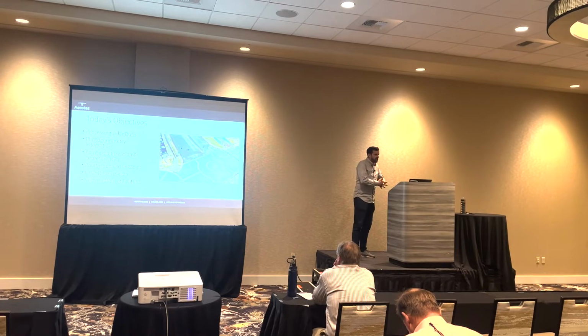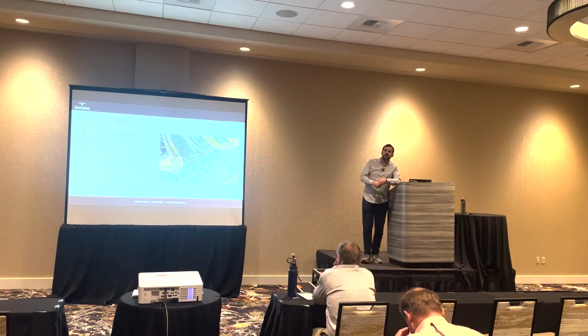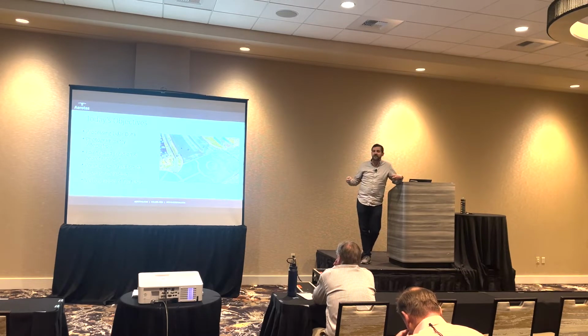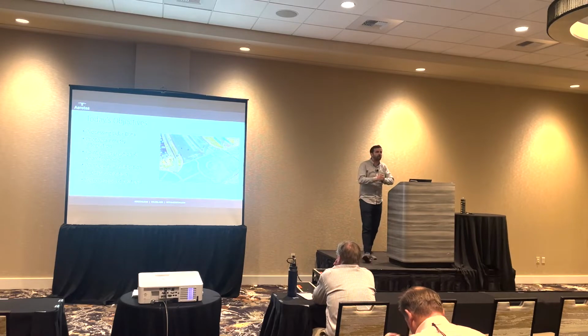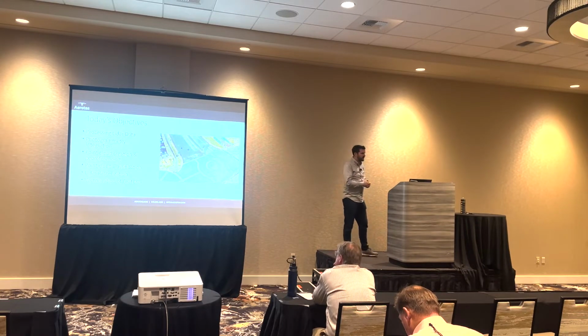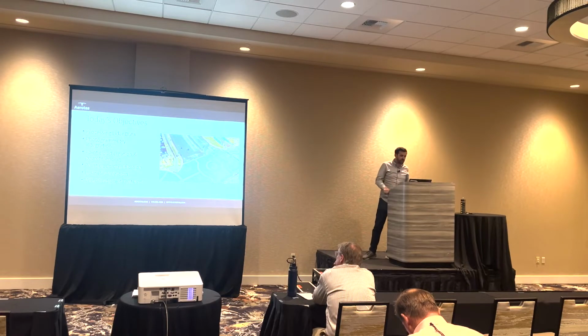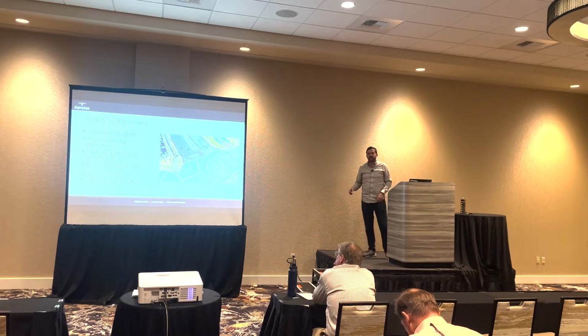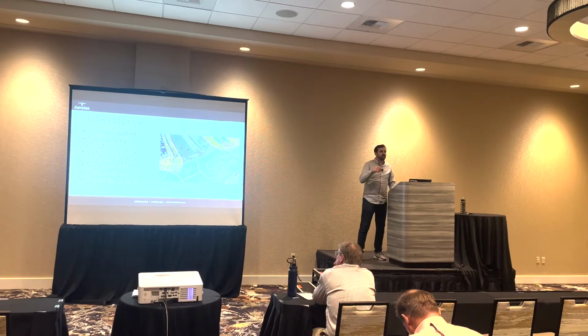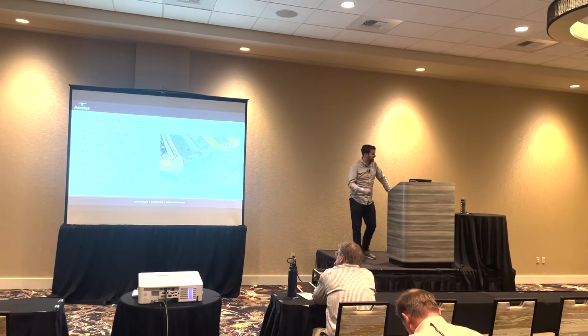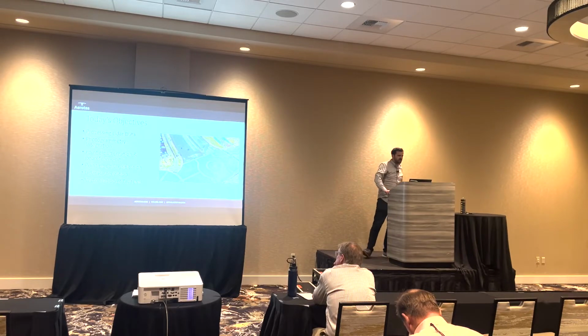So processing Lidar data, which includes photogrammetry integration. As I talked about yesterday, the best Lidar workflows, in our opinion, are those that actually blend photogrammetry and Lidar data together. That's the most optimal workflow to actually get high quality data out of your system. We're going to talk a lot more about point cloud creation, point cloud georeferencing, how do you classify it, what do you classify, what softwares, what algorithms, what settings to use, when AI makes sense and when it doesn't, when you need to go manual.